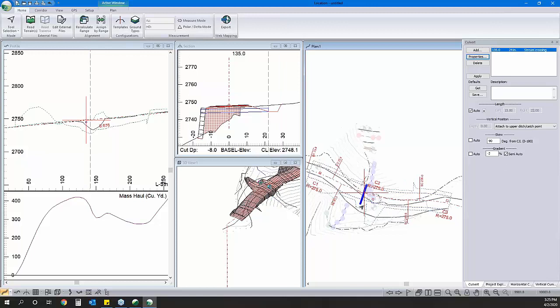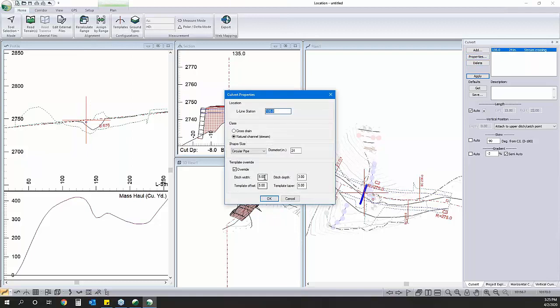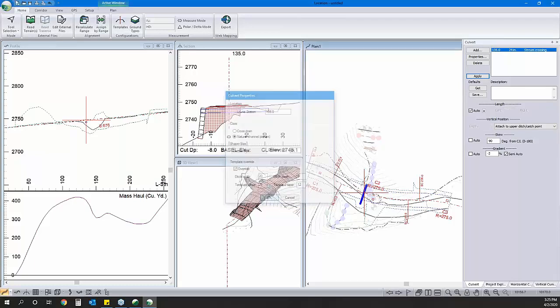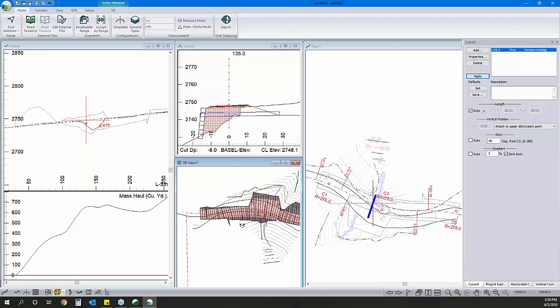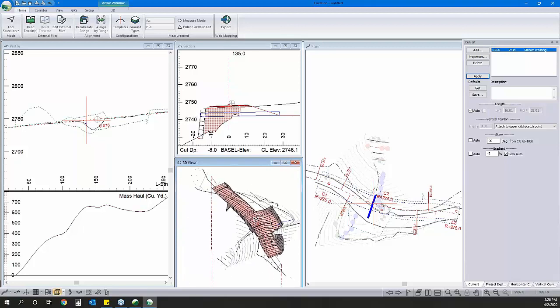But given our alignment of the site and the fact that that's already washed out the road, I think the dimensions that we already had are probably pretty close to good. So we want the ditch bottom width to be 20 feet. We'll go with a 5-foot depth, and we're going to make this long. So let's go 25 feet either side of our culvert, and let's taper it over 12 meters. So there we go. We've got a big hole. We can see that in our 3D view.